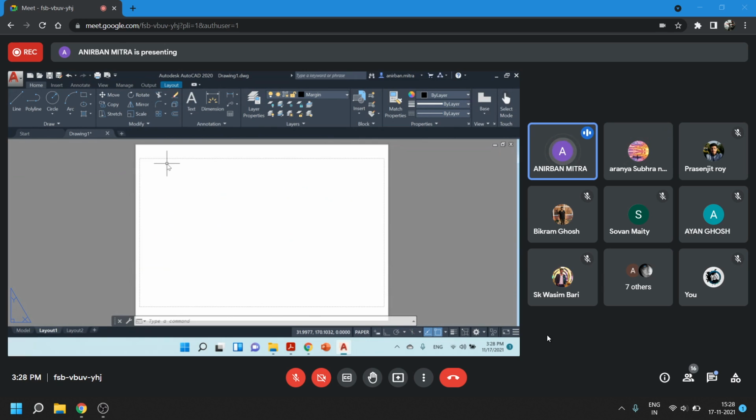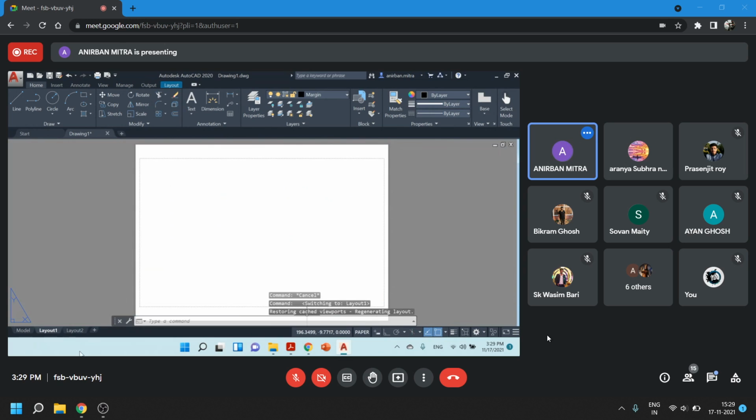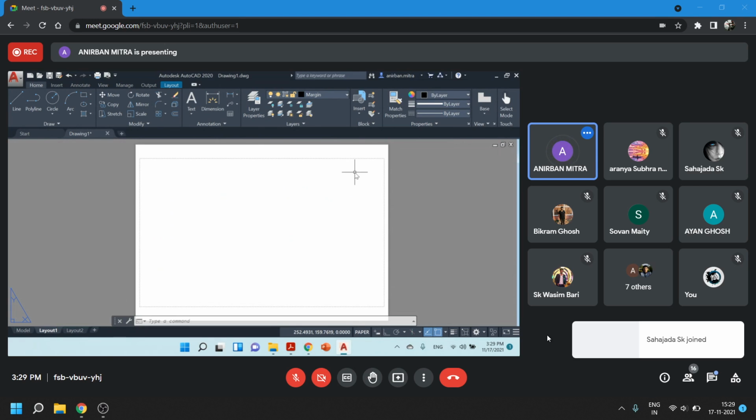By the way, in which space we are right now? The space we are right now in is paper space. That is correct. You can check it over here. This is the paper space. The model space is in the model tab. We have left it behind. We have gone to the layout tab, deleted the viewport, so we cannot access the model space from this layout tab right now, but we can bring in our own viewports later. So we are right now at paper space.